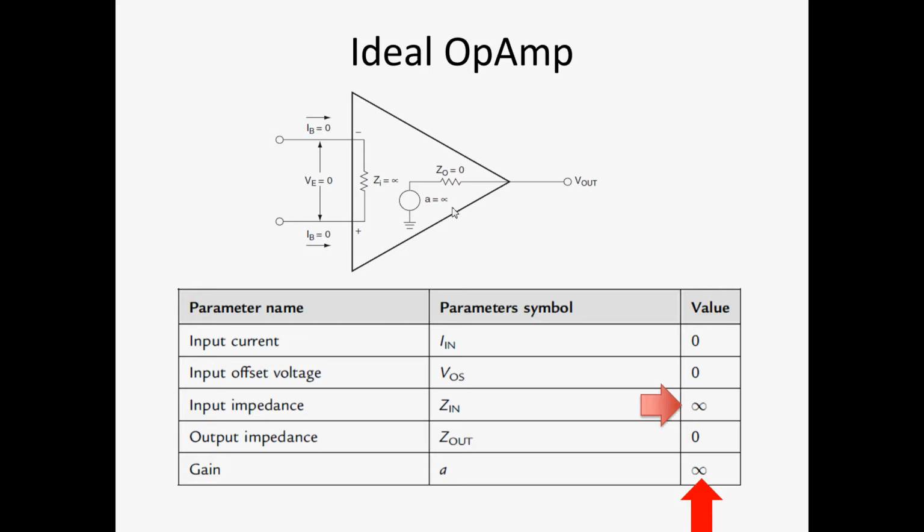Most importantly, real amplifiers are powered by something. So in these slides, in this schematic, you don't see any power. That's another characteristic of the ideal amplifier. It doesn't require power. Well, try to record the EEG without turning on the power of your EEG recorder. Do you think it's going to record the EEG? Not at all. So the amplification happens at the expense of the power supply.